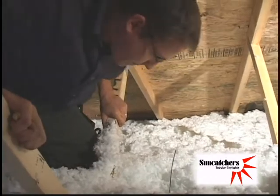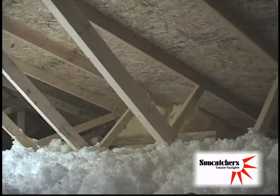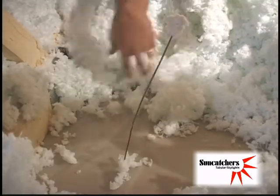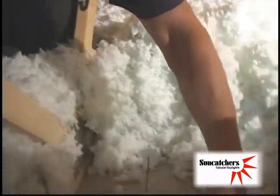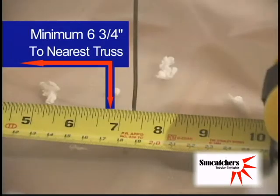Once inside the attic, locate the wire and double-check to make sure that there is nothing in the attic or roof line that could interfere with your installation. Remove the insulation from the area and measure the wire to ensure that you have a minimum of 6 3/4 inches from the wire to the nearest truss.